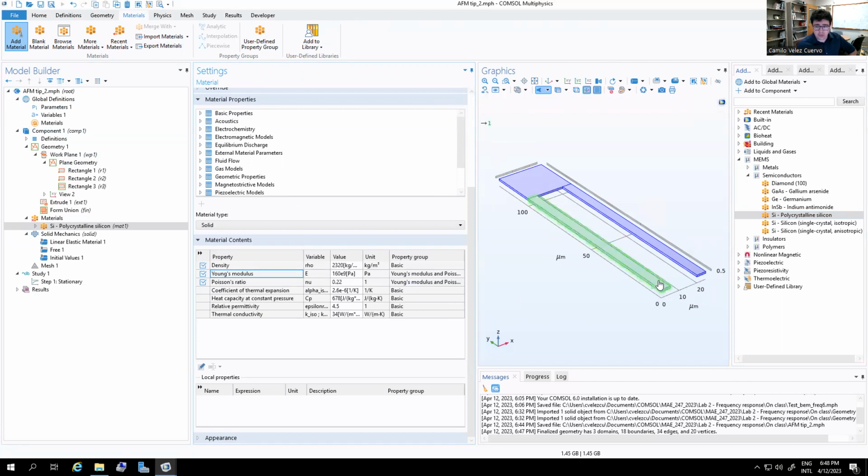So having each beam, because of these dimensions, we have calculated offline that the stiffness of the beam is going to be 0.2, and this other beam is going to have a stiffness of 0.2, so the combined stiffness is going to be 0.4. Those are two springs that are added in parallel.